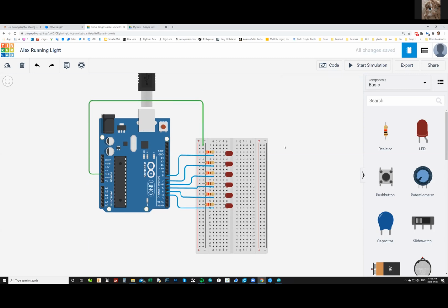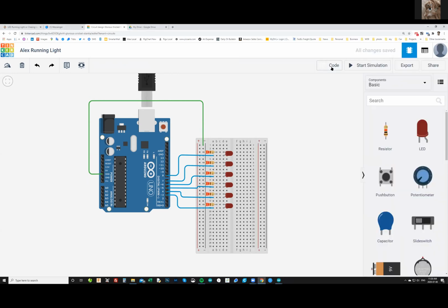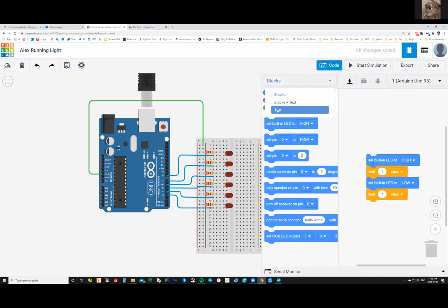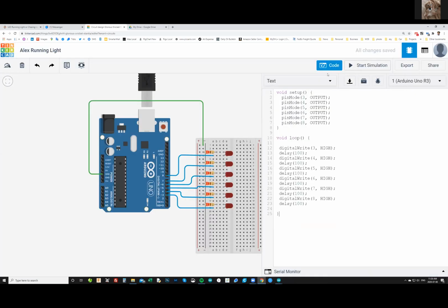And another thing you should always pay attention to is that on Alex's diagram, minus and plus are inverted. In his diagram, plus is on the side, minus is closer to the middle of the board. But on the actual ones, it's the other way around. So just pay attention to the signs, negative and plus, and don't try to follow the pattern. Make sure you're doing it smart and you're actually following the plus and minus signs there.